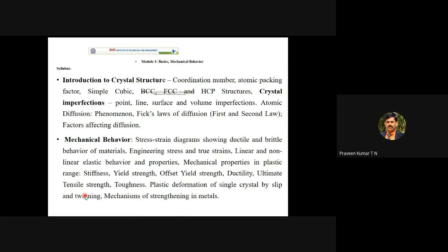In metals too, one crystal or grain has many subunits, and those subunits are nothing but your unit cells. So don't think that a single crystal means a single unit. You are analyzing the BCC structure or FCC structure when you talk about the crystal. The crystal is also referred to as the grain.